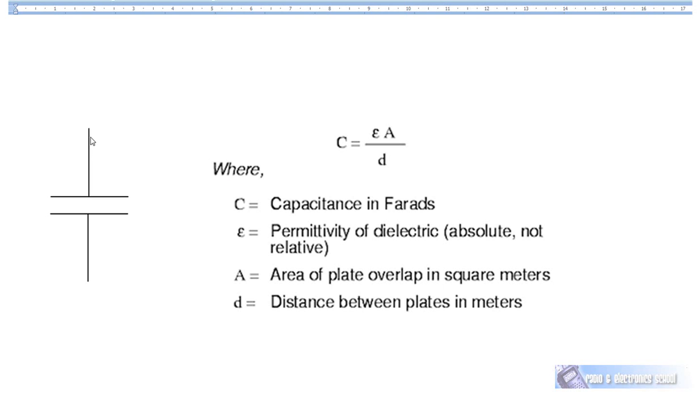If you were to put 1 volt across a capacitor, it will charge up. If we connected a battery to this capacitor, say with negative at the top and positive at the bottom, then electrons would run into the top plate, making the top plate negative, and leave the bottom plate, making the bottom plate positive.